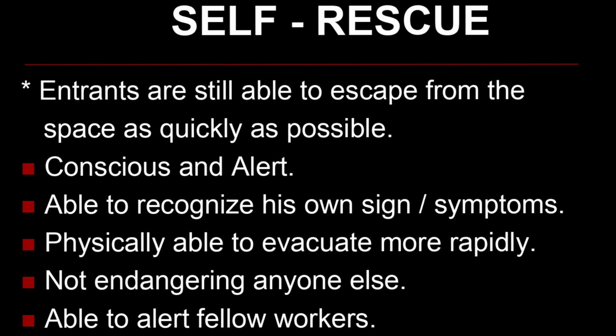Self-rescue. Entrants are still able to escape from the space as quickly as possible. 1. Conscious and alert. 2. Able to recognize their own signs and symptoms. 3. Physically able to evacuate rapidly. 4. Not endangering anyone else. 5. Able to alert fellow workers.